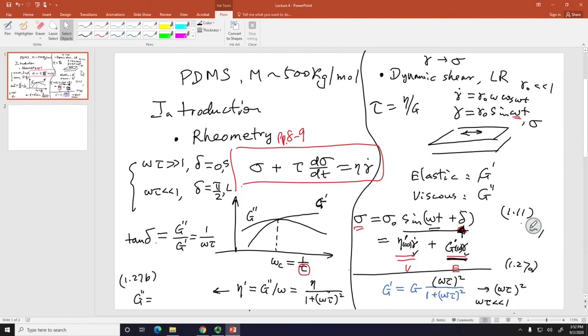If it's a piece of solid-like material with enough integrity, then you can hold it and do DMA. That's the point. In fact, you're missing half of the knowledge. DMA gives you viscoelasticity when you have a solid-like material. But for anything else, you go to the shear mode.